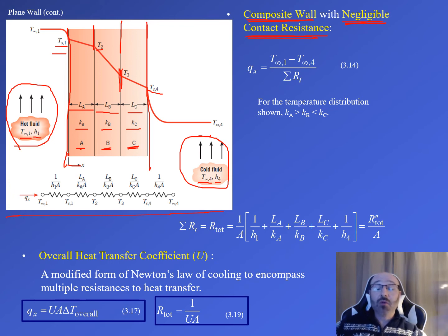And that's going to be important now as we go on and draw out our thermal circuits. So again, just like we did in the other one, I really do like to take advantage of the fact that we have that diagram there. We've clearly labeled what each of those interfaces and surfaces are between each of those, and use that to draw out our thermal circuits. So you can see I lined up right here, here's your first, 2, 3, and 4, lined right up with those nodes on our thermal circuit right there.